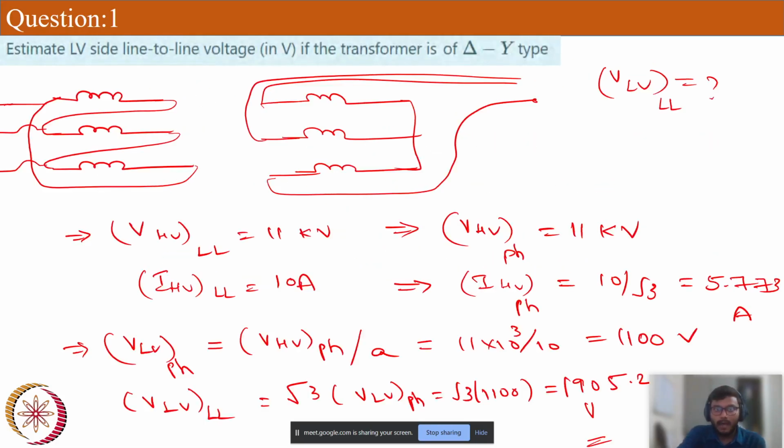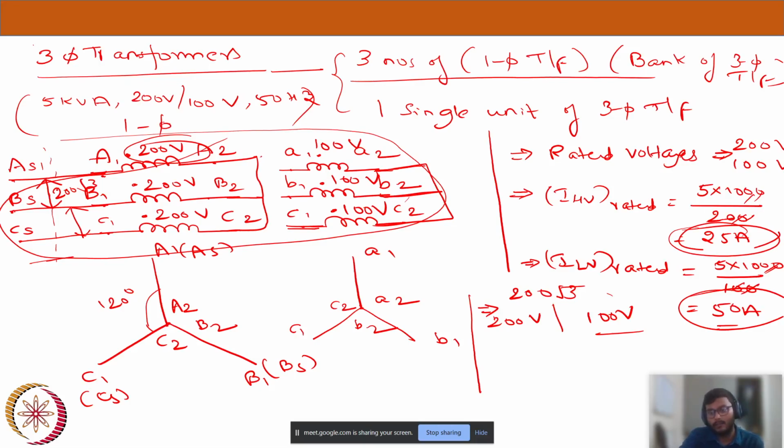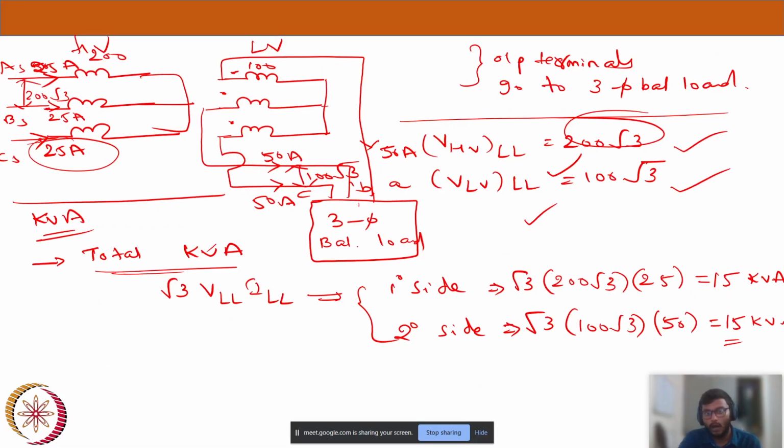So let's have a quick summary of what we have discussed today. We started our discussion with three-phase transformers, how we can construct a three-phase transformer with three single-phase transformers of known ratings, and what rated voltage should be applied so that my windings won't be overloaded. We saw the phasor diagrams of the primary and secondary windings, and next how we can calculate kVA ratings of the transformers, and if I connect a balanced load, what currents my windings should draw, and the restrictions on the currents.